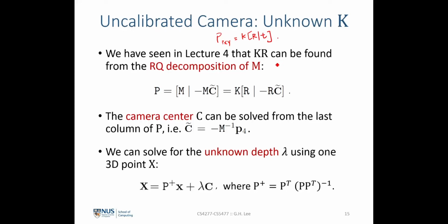And in order for us to reach our objective of finding the camera pose with respect to the world frame, which is essentially the rotation and translation, also known as the extrinsic values of the camera projection matrix, we have to do a decomposition of the 3 by 4 camera projection matrix into the intrinsics, which is K, as well as the rotation and the translation vector over here.